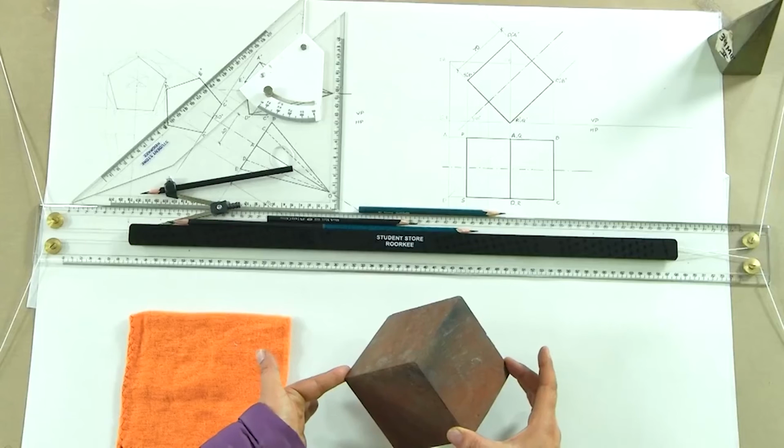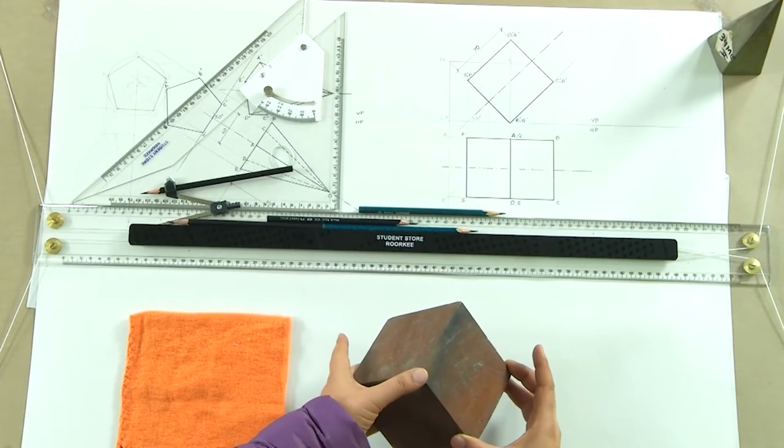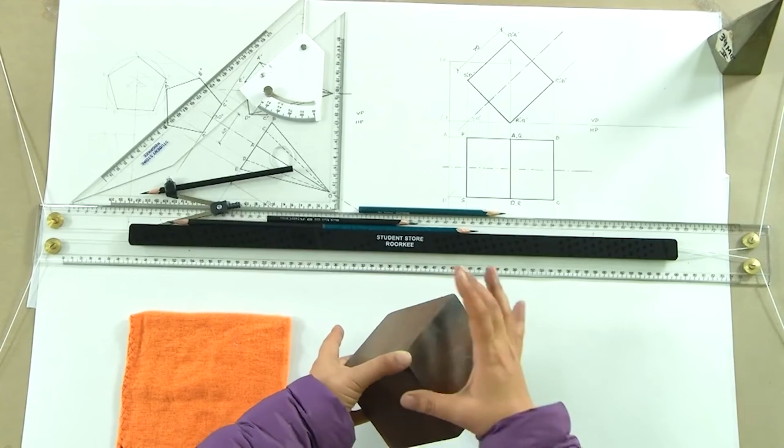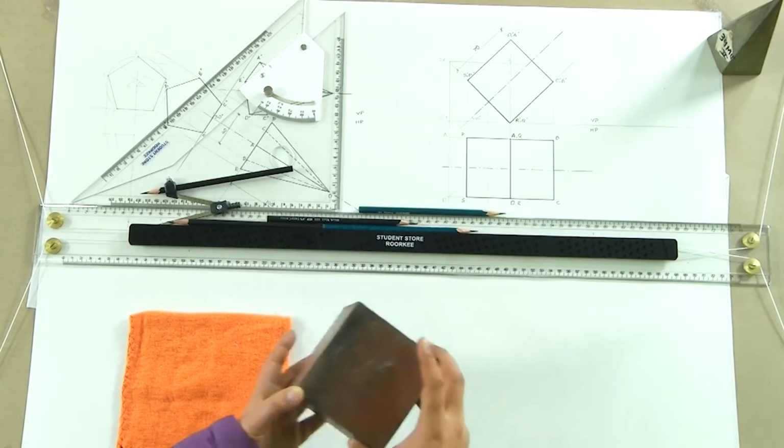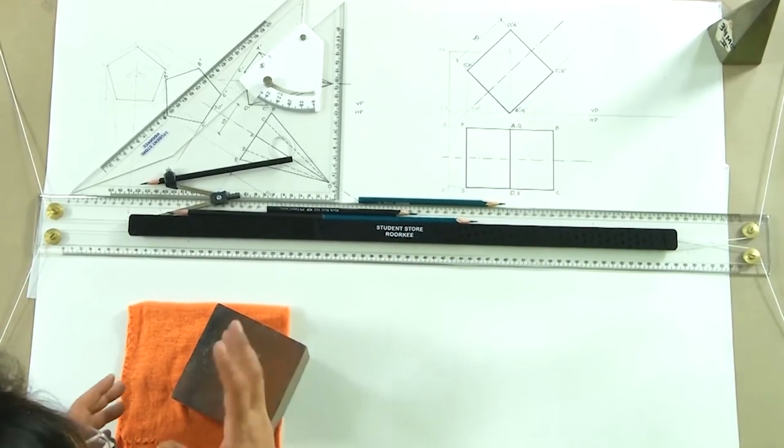So, when you see it from the top, tell me what do you get? So, you have to draw it at home and then you have to figure out what do you see, how many faces from the top do you see, and what is the shape of each of these faces. Do you get rectangles like this at right angles, or do you get some different shape? So, I hope with these two examples, you have fairly understood how to draw the orthographic projections of solids which are inclined to one of the reference planes and the axis remains parallel to the other reference plane.